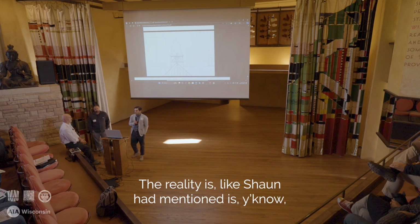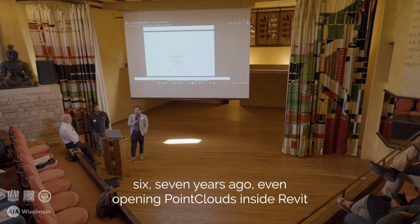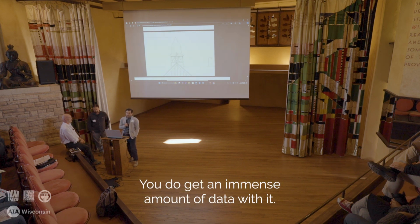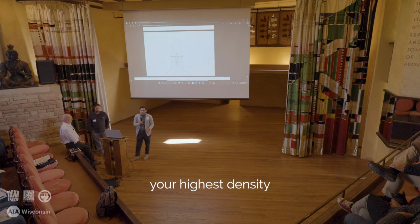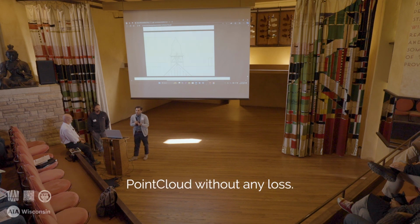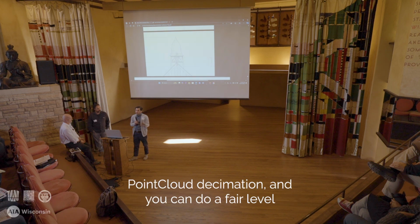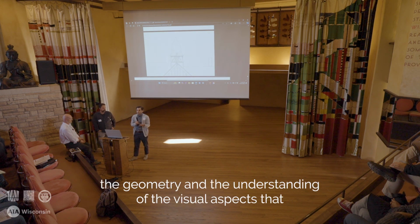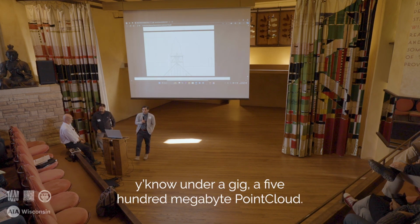The reality is, and like Sean had mentioned, six or seven years ago, even opening point clouds inside Revit was a challenge. You do get an immense amount of data with it. So I think the goal would be to maintain your highest density point cloud without any loss. And then you can export versions of it where you're doing point cloud decimation. You can do a fair level of point cloud decimation that allows you to maintain the geometry and the understanding and the visual aspects that you would need working with the files. And you can get files under a 500 megabyte point cloud.